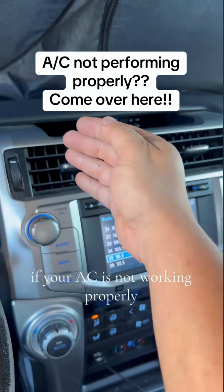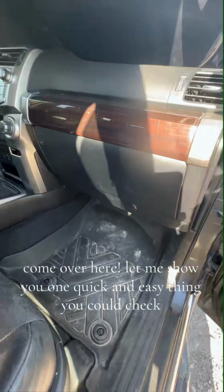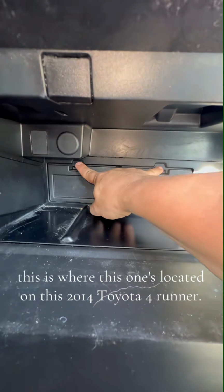If your AC is not working properly, turn the AC full blast. You can hear the blower motor get louder, but it's still got low airflow. Come over here. Let me show you one quick and easy thing you could check that will cause that issue. Cabin air filter. This is where this one's located on this 2014 Toyota 4Runner.